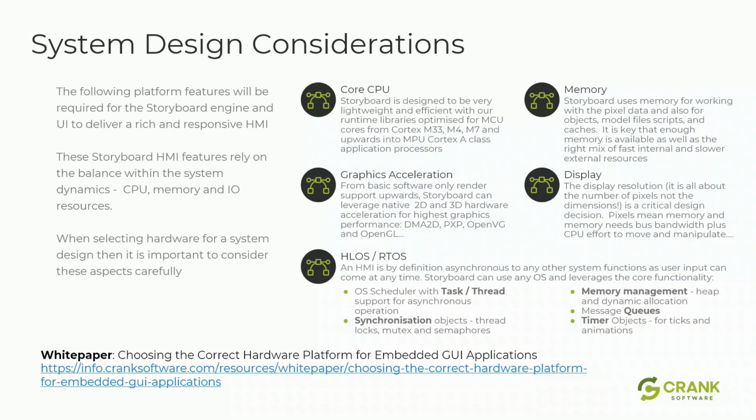Memory is a big thing. So memory is probably one of your key considerations. Storyboard uses memory, of course. We use it for model data, but also primarily for the pixel data, so this is the raw images and things. So it's important that there's not only enough memory, but there's also the right mix of it, whether it is faster internal memory or slower external memory.